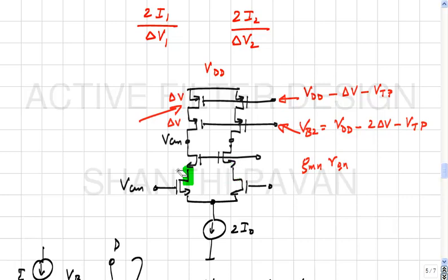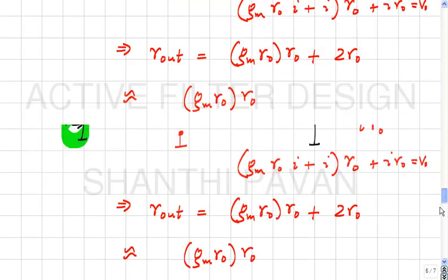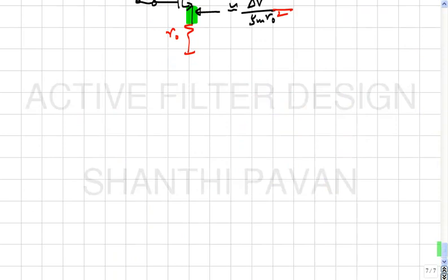All right. So, one more thing that we should generally be wary of in analog design is when you seem to be getting something for nothing, always there is likely to be a catch, right? So, here we seem to be increasing the output impedance, but you added one more device which also adds noise. So, there are three possibilities. The extra noise is very small compared to what was already coming out, in which case we are happy. The extra noise is equal to the noise which is already coming out, in which case it's bad. The extra noise is much larger than the noise which is already coming out, in which case it's very bad. Okay. So, before we jump to conclusions and start putting cascodes all over the place, one thing we ought to do is to see what effect the noise of the cascode has on the